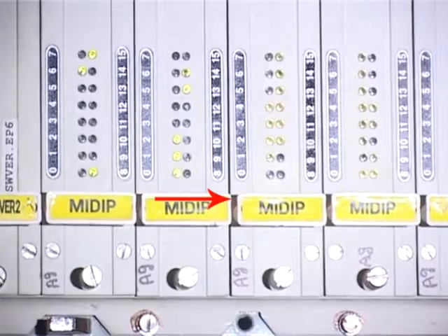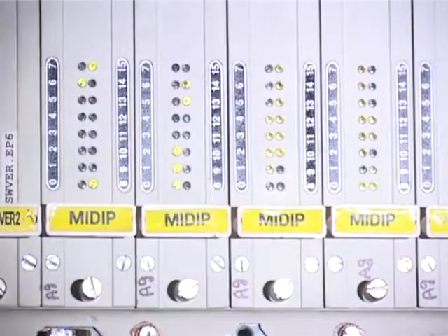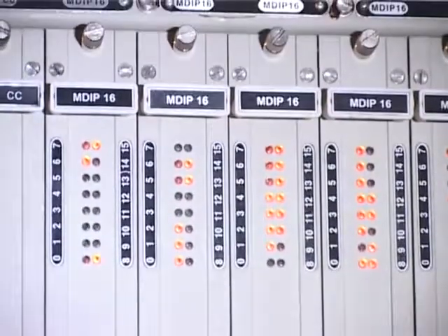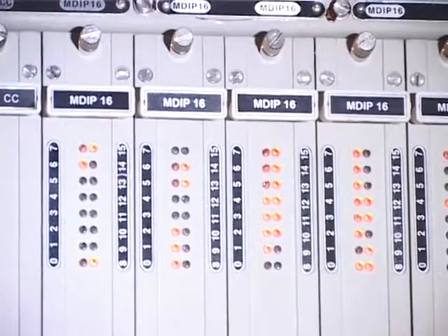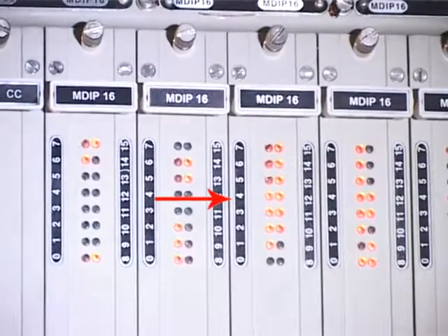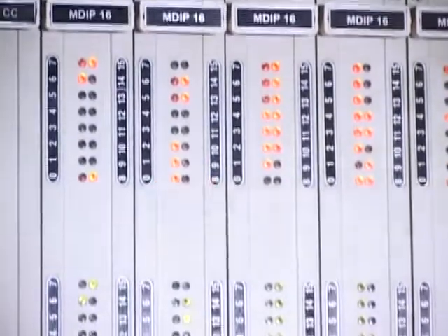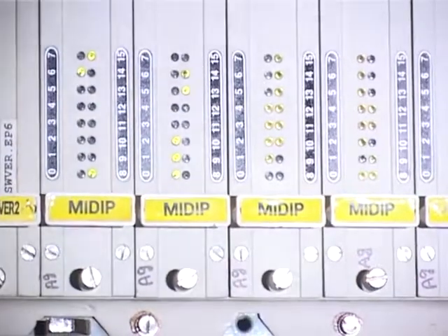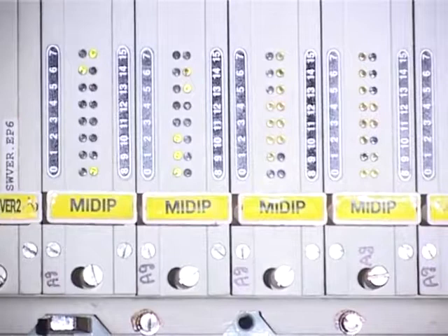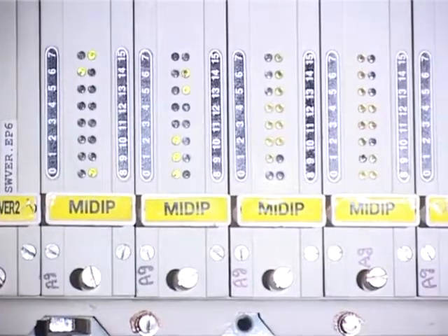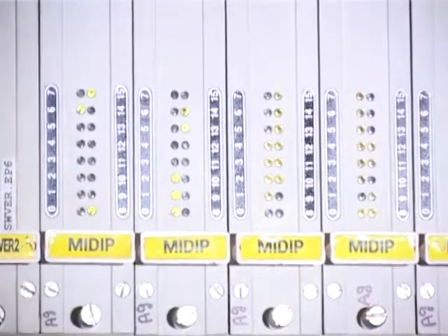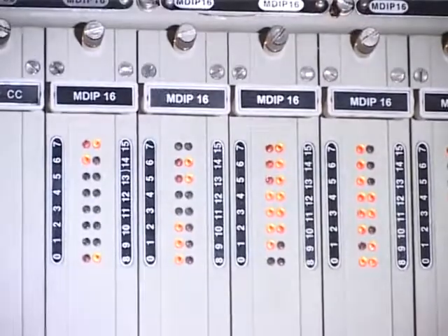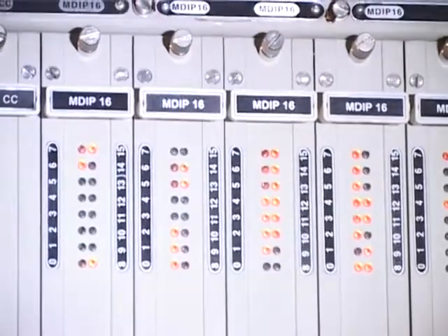Digital input cards MDIP16, MIDIP16. These digital input cards consist of the hardware required for converting the high voltage signals of nominal 72 volt DC from the locomotive circuits to isolated low voltage signals of 5 volt DC required for the microprocessor of the system. The green LEDs provided on this card indicate presence of 72 volt DC on that particular channel. The yellow LEDs indicate the signal being sent to the microcontroller after isolation and signal conditioning.